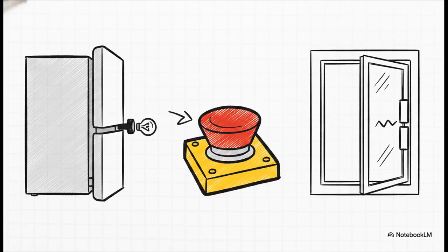When the fridge door is wide open, nobody is pressing the switch. Because it's a B contact, electricity is flowing by default, keeping the light on. But when you shut the heavy door, it literally presses the switch, just like stepping on that hose, cutting the power and turning off the light.